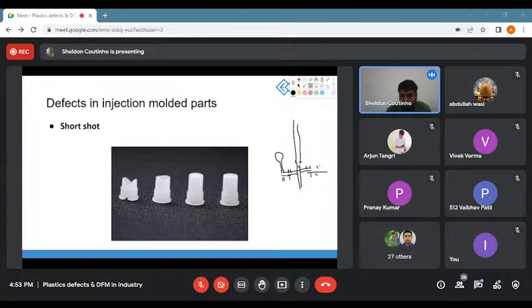So say this is sub runner 1, all the spoons are properly made; sub runner 2, all the spoons are properly made. But when you look at sub runner 3, the spoon that will be made here, or the one being made here, these spoons may fall short in material, because of course it will fill from the side that you are filling it in. So you need to do a proper mold flow analysis and understand the volume of material needed.